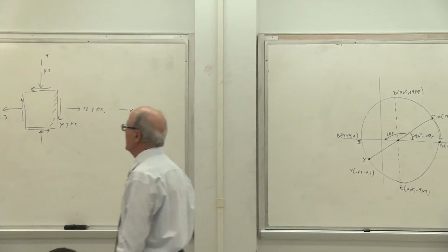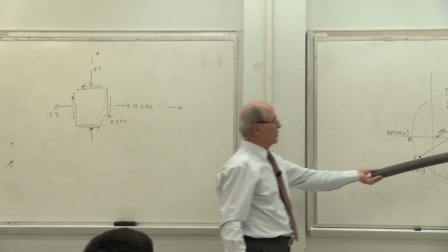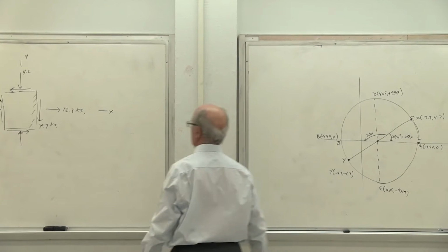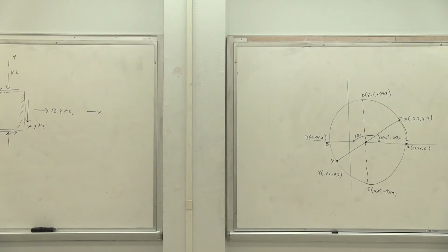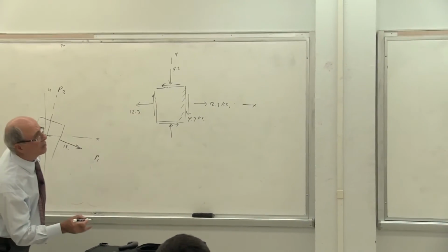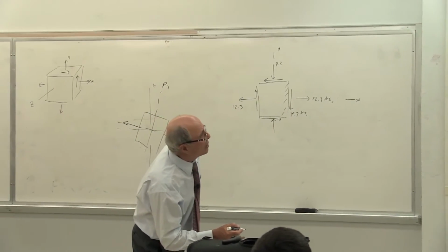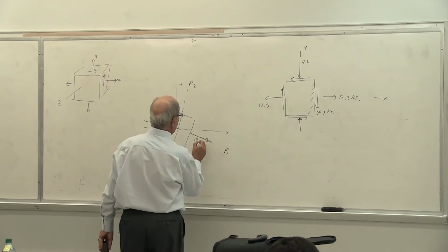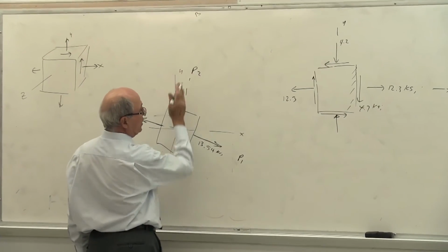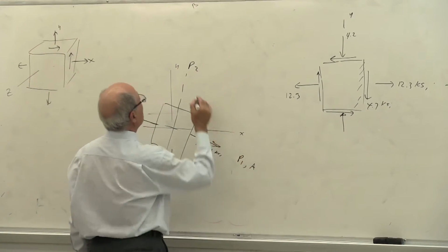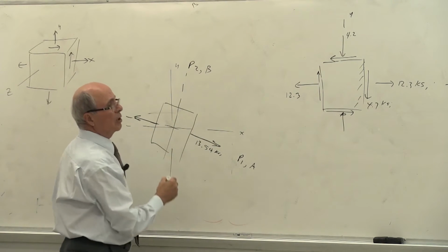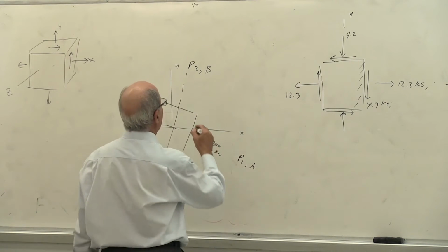What do I put at A? At A, I put this and 0. It's very important, everybody, and there is no shear stress. So therefore, I put here 13. It's in tension. So I put here 13.54, whatever it was, 34 or 54? 13.54. So 54 ksi. And on the other side, because Y becomes P2 or B, X becomes P1 or A, this becomes P2 or B. Either way, you can show it like that. And that one was, of course, a negative of 5.4. So this is it.